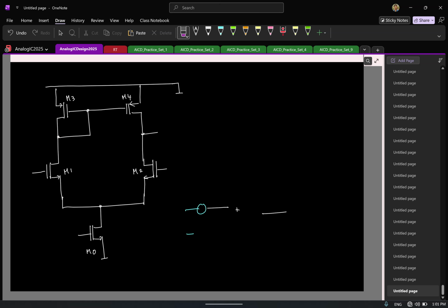So we are only finding the effective differential input referred noise voltage. So again, for finding the input referred noise voltage, what will I do for RS? RS is 0, which means the inputs are shorted here. Because remember, ideally you have an RS and then the small signal voltage V1, V2. For finding the noise, we are making the small signal input voltages V1, V2 0, and RS is also 0, so that essentially is a short circuit.